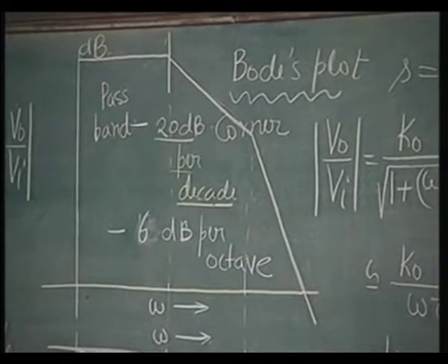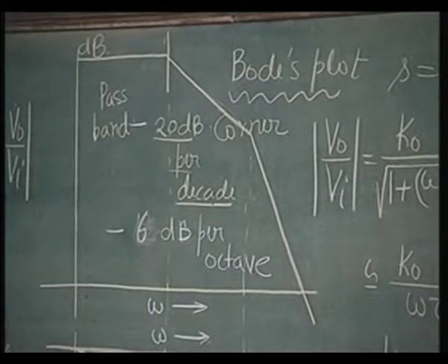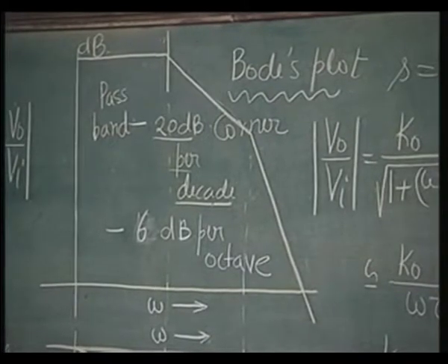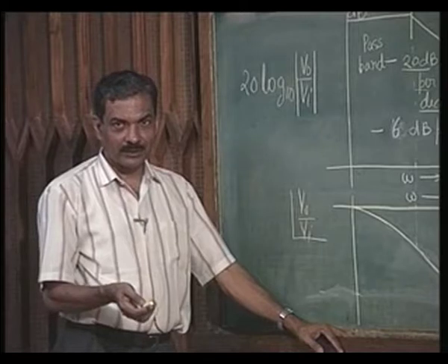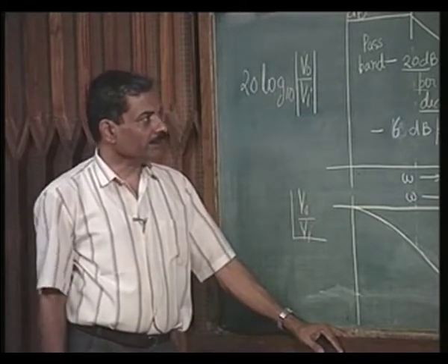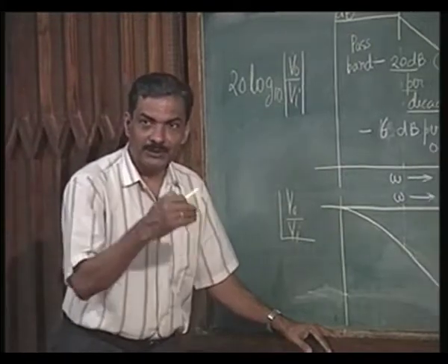Now, something regarding the phase shift also is important. Therefore, these non-idealities come into picture in any amplifier. This is also a performance factor, which is as important as input resistance, output resistance and gain. So, this is another performance factor. It tells us up to what frequency it can be used.